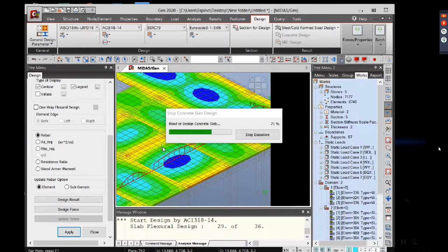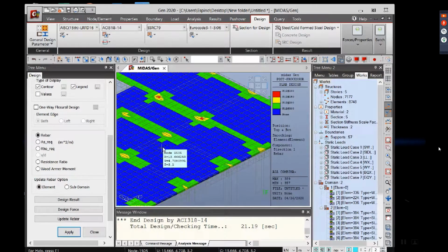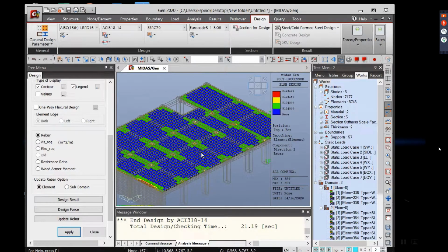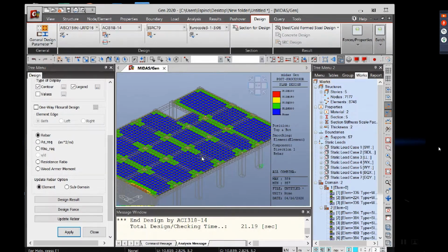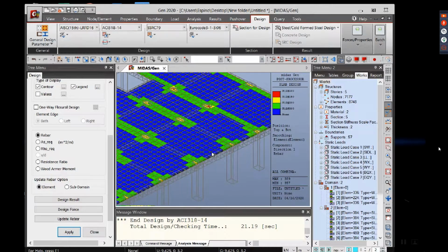Of course, having a finer mesh means having a more exact result. But you will also have to consider the post processing and the analysis time that the computer will use, since many elements means a larger analysis time.